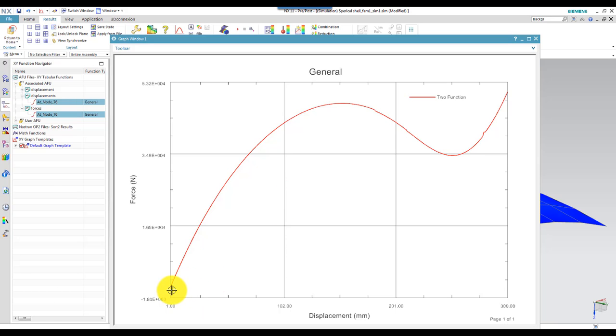This is the snap-through behavior. Here you see the displacement from, it's not 0 but 1 to 300, and here you see the load. And what's interesting here is that we actually applied displacements as increments up to 300, and at each step we have a unique solution. So by applying the displacement, or using displacement control, we were able to capture the snap-through behavior. And we see that the forces look to be in the right region compared to the results we have in the paper.